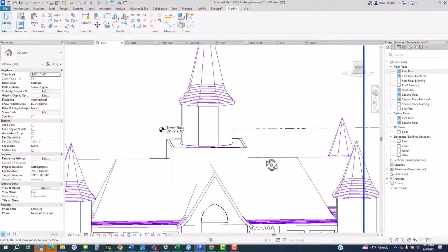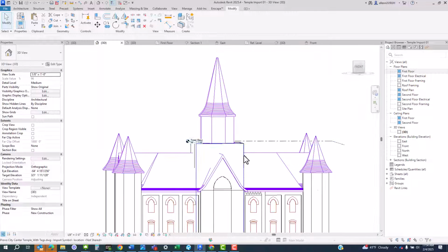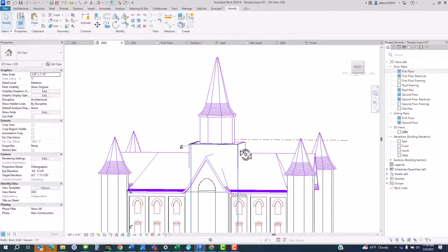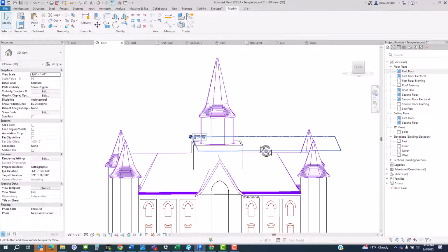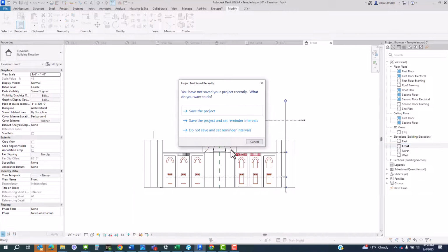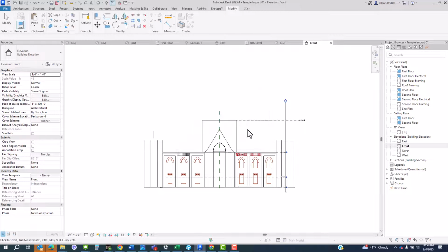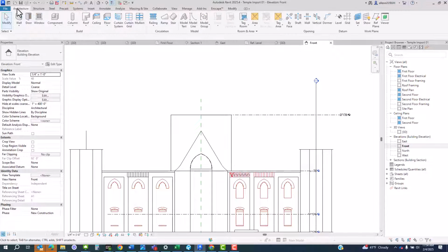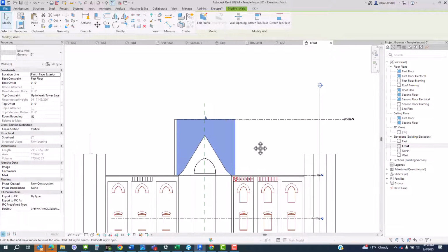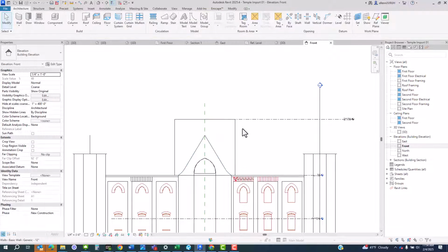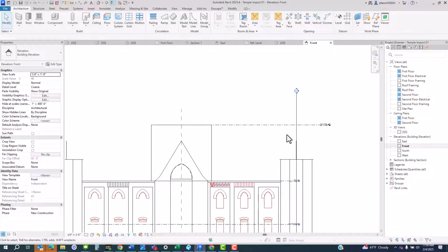To begin with, I created myself a datum because I want to create these walls and have some kind of a foundation for my tower. So I created a new reference level, which you can do just by going to any one of your straight on elevation views. I went Architecture, Level, created a new level, and then when I started drawing these walls, I was able to extend them directly up to their new level.